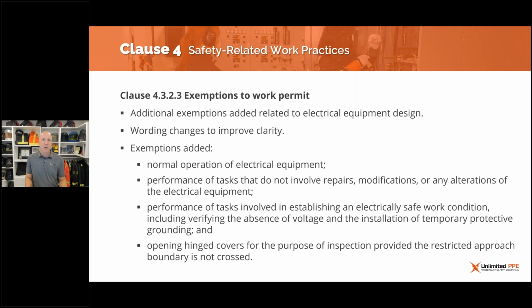And the last one here has always been, I guess, a stumbling point for most contractors for sure, and probably a lot of industrial and manufacturing employers: opening up hinge doors, so hinge covers, for the purpose of inspection, provided the restricted boundary is not crossed. So this does then allow, provided that you follow the requirements of the clauses in CSA Z462, for workers to open up a hinge cover for the purpose of inspection, again, provided they're not crossing the restricted approach boundary and not requiring an energized electrical work permit to do so.